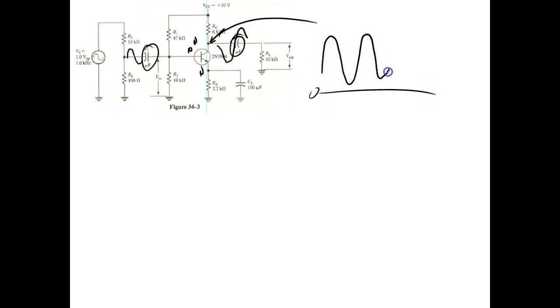Transistor amplifiers are DC amplifiers. But we can make it appear to amplify AC by using what? By using capacitors. So the capacitors will let us put AC into a DC system and subtract from the base voltage, right? You understand that? And allow us to generate DC at that collector right there. So if we looked at the collector, what we'd see, this would be 0 volts, and the signal is going to be doing this. It's riding on DC.